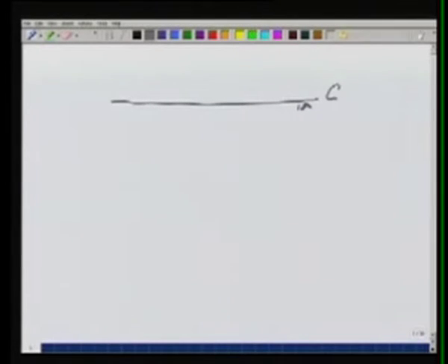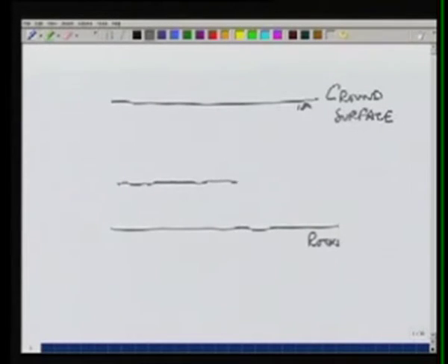In surface water, we have already looked at various kinds. This may be pond, lake, streams or oceans. In the subsurface, let's look at a cross section of the ground. So let's say this is the ground surface. And there may be a bedrock which is impermeable, so water will be staying on top of this. And this portion shown here by this line, below this all the soil pores are filled with water. Therefore, this is known as saturated zone.